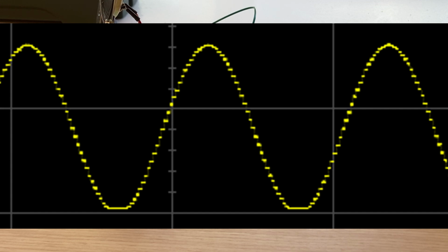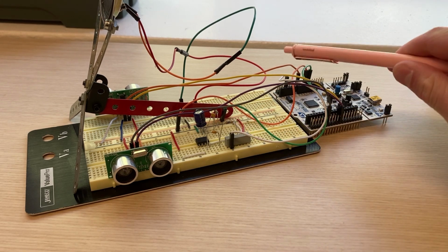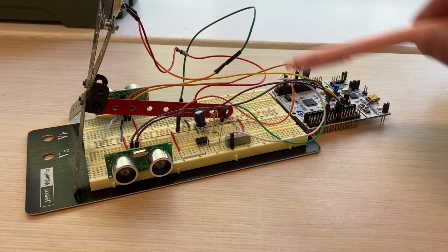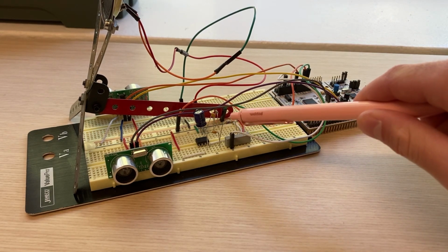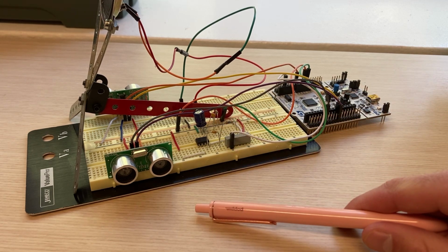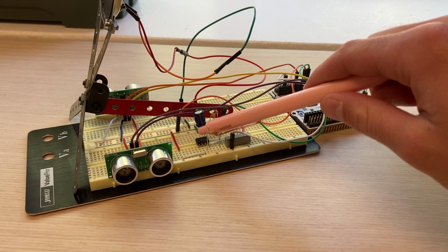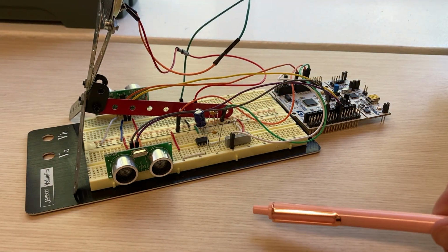Now, when we're playing our highest note, C5, which is a 523 hertz sine wave, the DAC is going off over 33,000 times per second. So it has a pretty high frequency. Now, once we get our sine wave here, we go through a variable resistor, and then we have a low pass filter, which is used to center our sine wave at 0 volts. We pass through this amplifier and ultimately make our way here to the speaker.